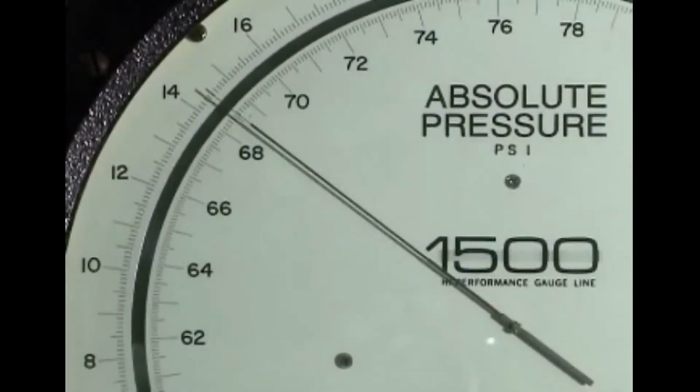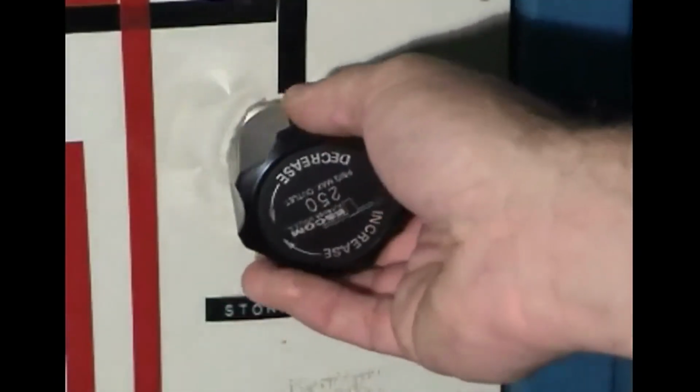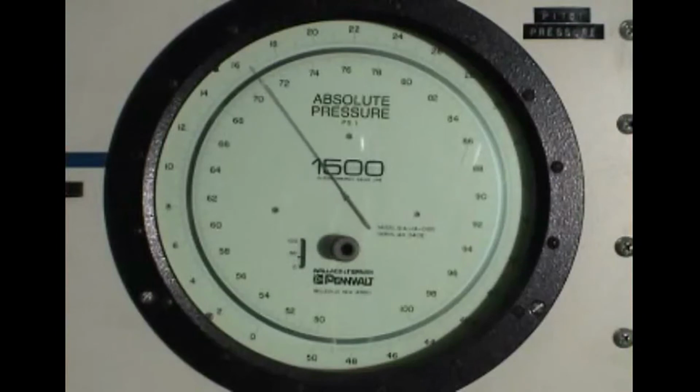This is another instrument based on the same principle, but designed to read absolute pressure. It reads about 14.4 psi when open to the atmosphere at the altitude where these experiments were done. If we apply pressure above 1 atmosphere, the reading increases above 14.4 psi.